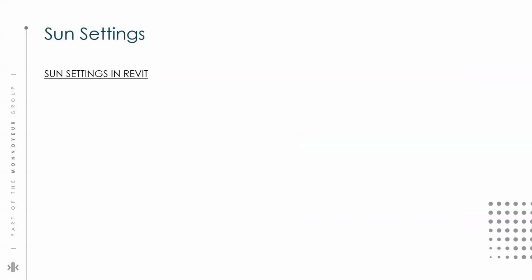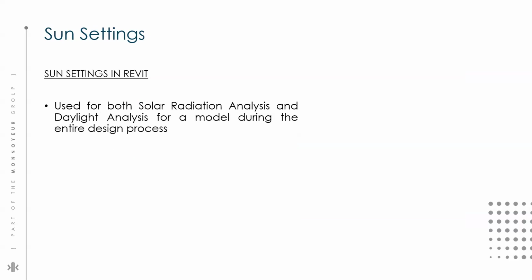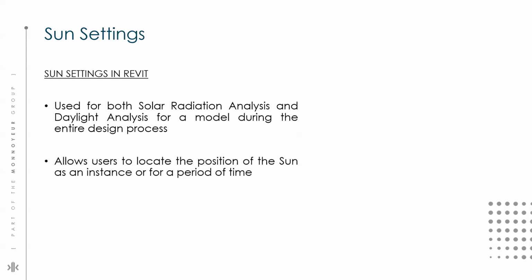The first portion that comes whenever we move on to the interface is how we need to utilize the sun settings. The first thing is to set up your own location, and then you should have particular timings where you need to judge on the basis of solar and shadow analysis, and its advanced settings. Whether you need a still sort of setting, a single day solar analysis, or multiple day solar analysis, all those things can be predicted in Revit.